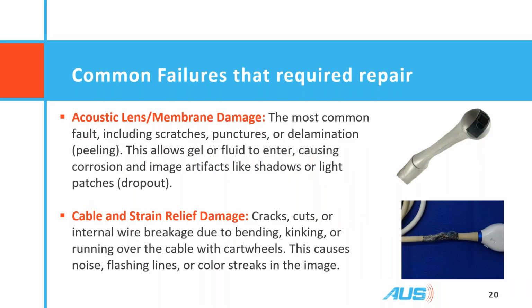Any damage to the acoustic lens or membrane, you should immediately remove that probe from service and get it repaired or replaced. Again, we offer loaner probes, so you shouldn't be without a probe. But it allows gel or fluid to be intrusive, get inside to cause more damage to the backing material, to the electronics. And it can also allow electrical shock to reach the patient.